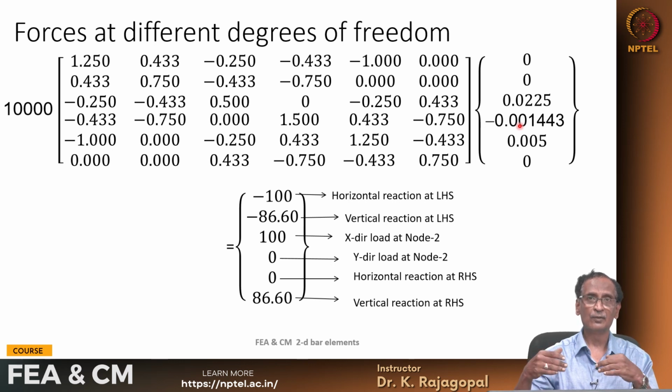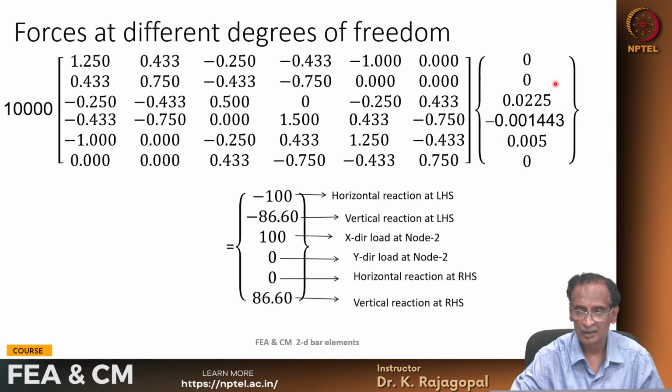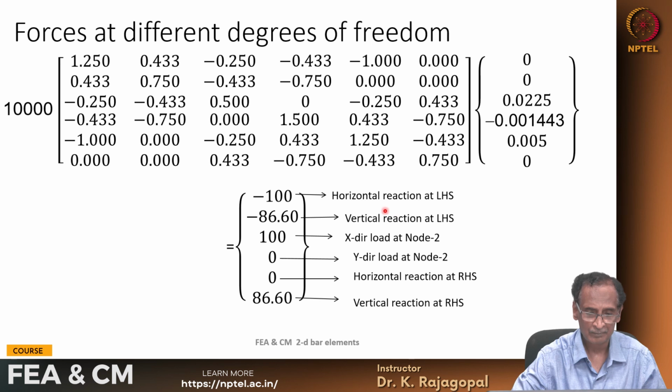Like we can go in for a stiffer element, like a bigger cross section to increase our stiffness AE by L, or change the material, okay, and then we can get our displacements within control.